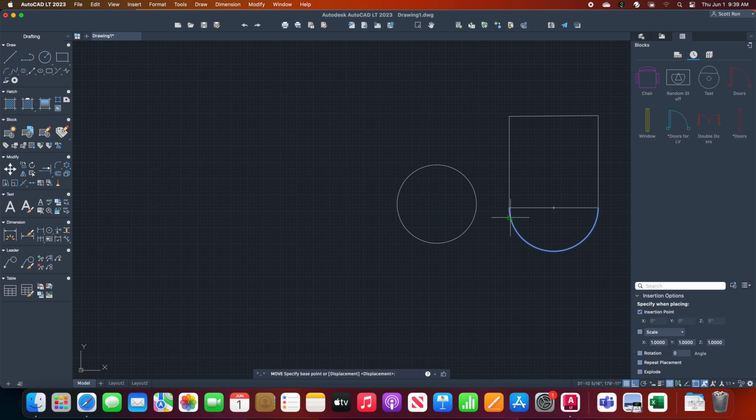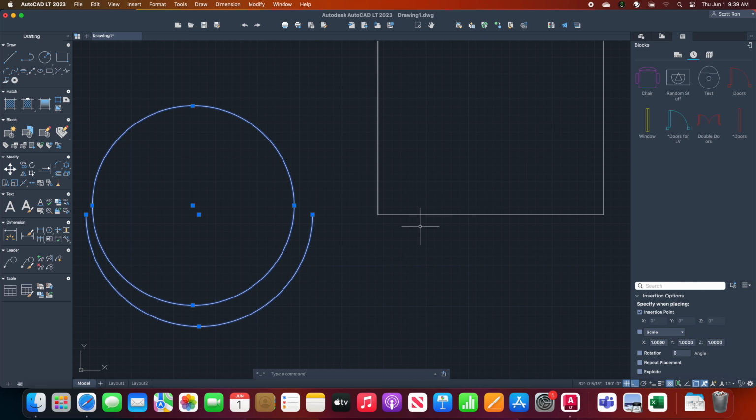No, I don't think that's how it should be. Because clearly it's bigger than 6 inches, because I do know that that circle is a 6-inch radius. I think if you're trying to fillet from one line which is not perpendicular or attached, not intersecting, if you just select fillet, it's just going to make an appropriately sized arc to join the two lines, not 6 inches. Because filleting basically means rounded edges, right? But here, this line and that line are not necessarily joined together. I mean, they're not intersecting.